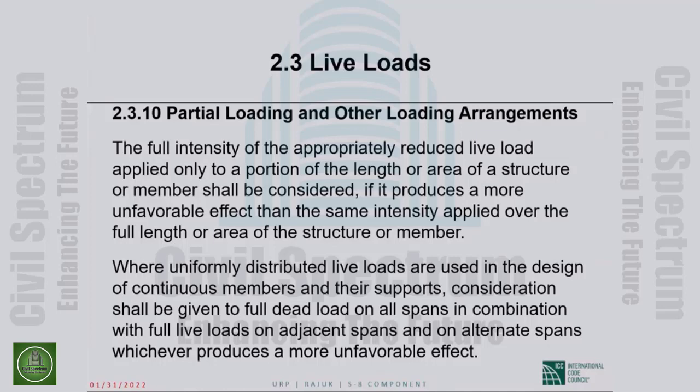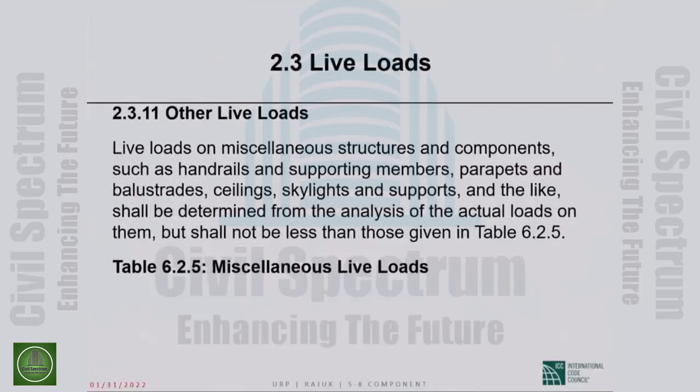It's labor intensive, and the benefits are kind of limited. So more and more these pattern live loads are just not done in design offices. I do not know that it is a violation of the code. It is just like moment redistribution, which is simply not done anymore. I'm not telling you don't do it, but all I'm telling you is that the current circumstances typically don't allow you to spend that kind of time.